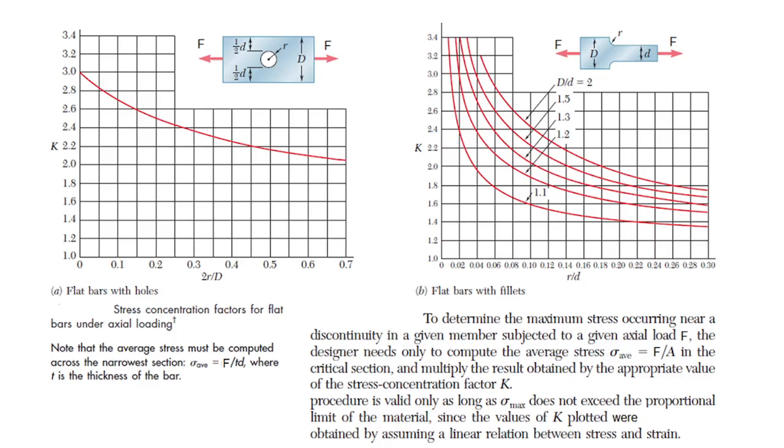To decrease the computation time, and to be able to use an ordinary computer for solving such a problem or analysis, in the vicinity of abrupt changes and discontinuities, empty spaces, use smaller sized finite elements.